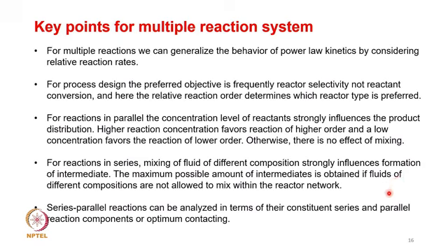Maximum possible amount of intermediates is obtained if fluids of different compositions are not allowed to mix in the network. And of course, you can also have a series-parallel reaction, and you can analyze it in terms of its constituent parallel and series reaction components for optimum contact and optimum flow, leading to optimum sizing. And as we have learned before,